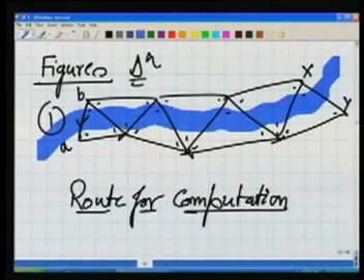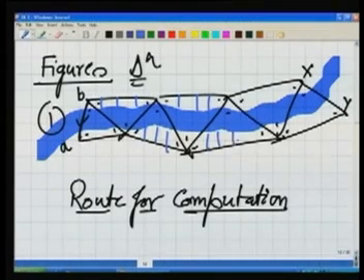So this single chain of triangles will be a very good figure. You just establish this and then start plotting the offsets. You will be able to plot the boundary of the river. So this figure is good in this kind of scenario, but not always.